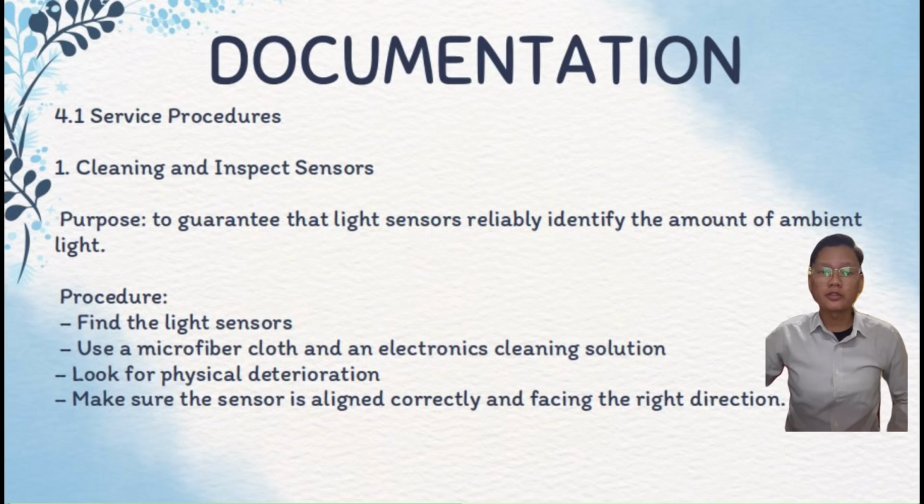Second, use a microfiber cloth and electronics cleaning solution to carefully clean the sensors. Look for physical deterioration that might make identification more difficult, including cracks or scrapes. To detect light, make sure the sensor is aligned correctly and facing the right direction.